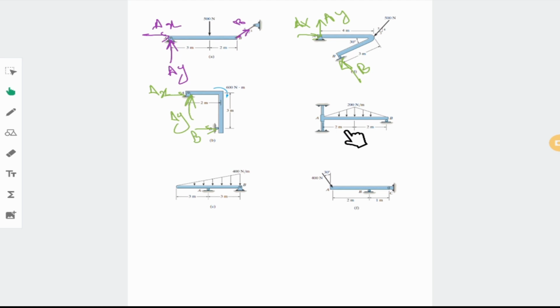The other kind of joint that we may have is like this. They may name it slider or collar or something like that. The way this joint works is like this. It lets this slider go up and down, but does not let it go to the left and right, and it does not let the rotation, meaning that if you start to rotate this piece, you start to break the whole joint. This applies two reactions for you.